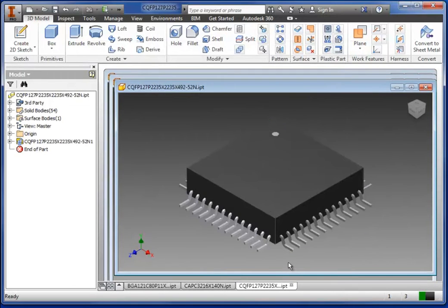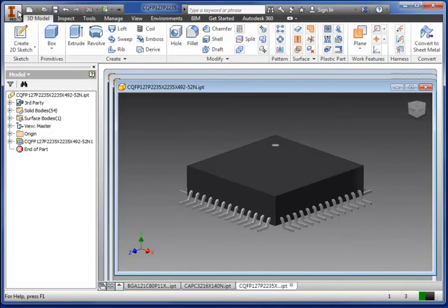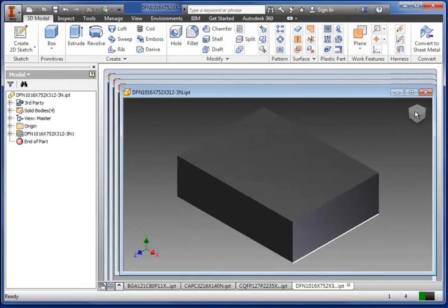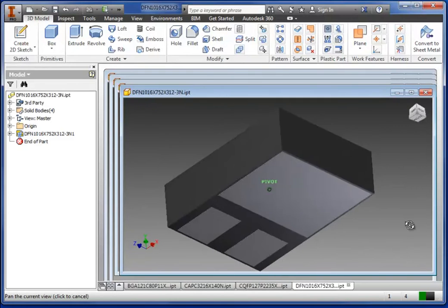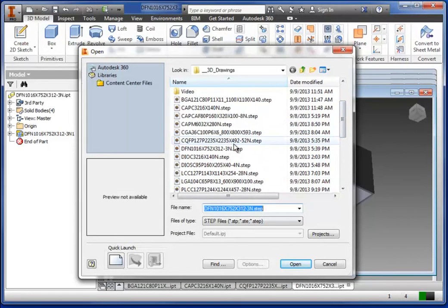other user-definable color patterns. Browsing the CQFP, notice the automation of the marker code for the pin 1 and the orientation. Next, let's bring up a DFN part with the different leads, sizes, and widths automatically generated, matching the PCB footprint land pattern model, which we exported to Allegro or a host of other EDA tooling systems.